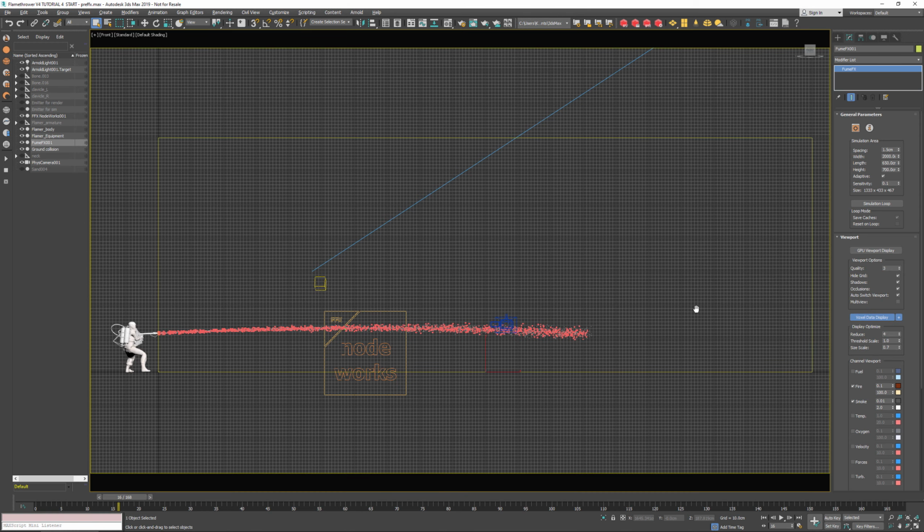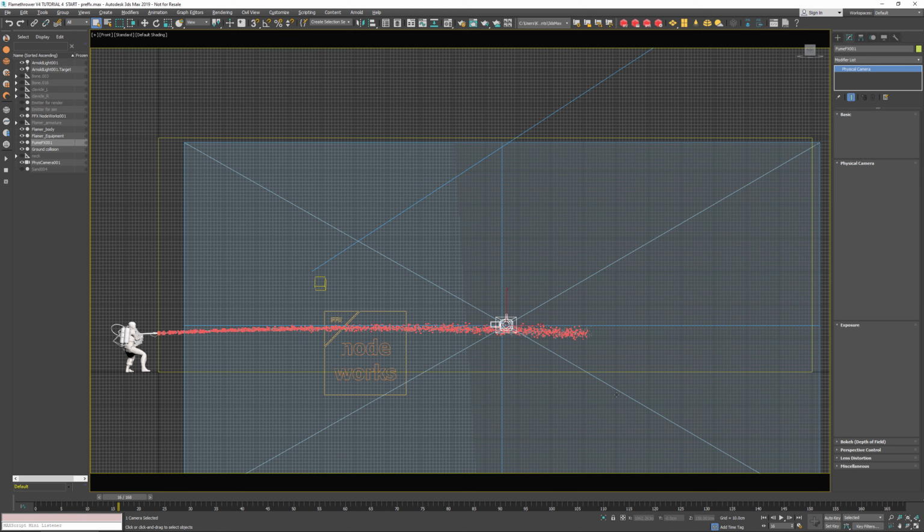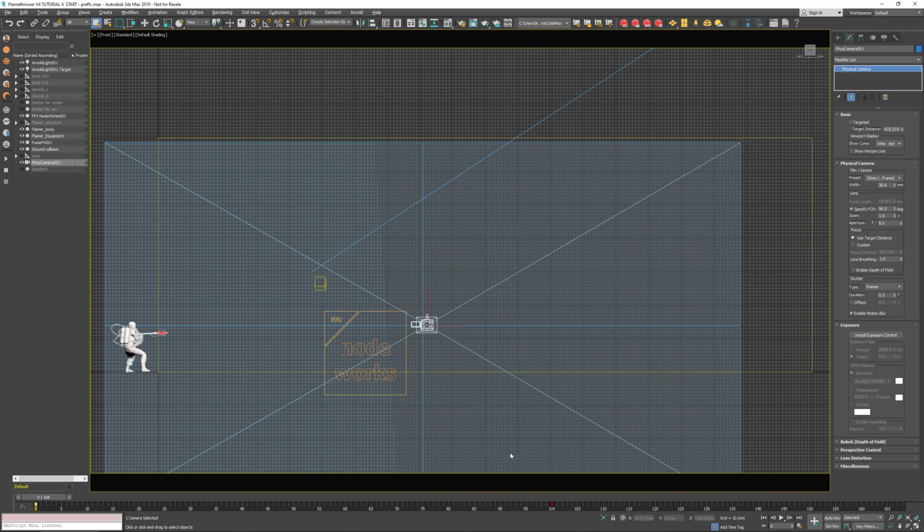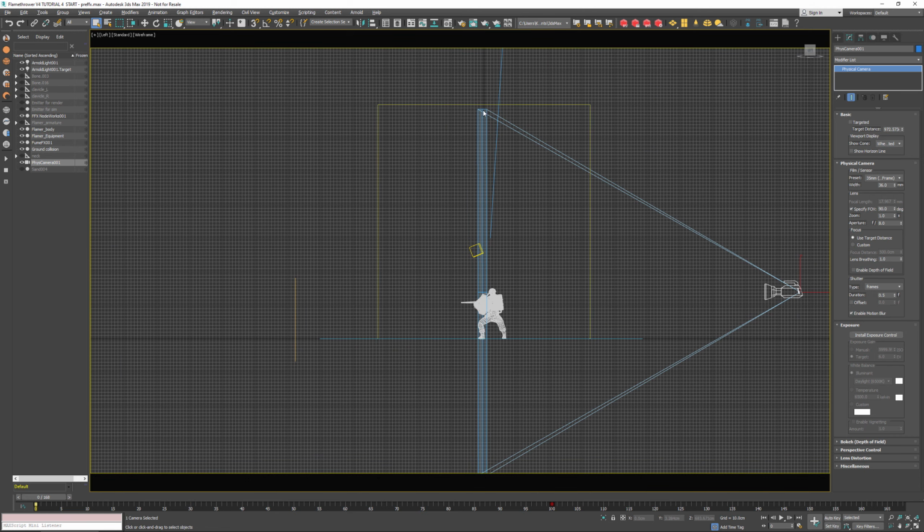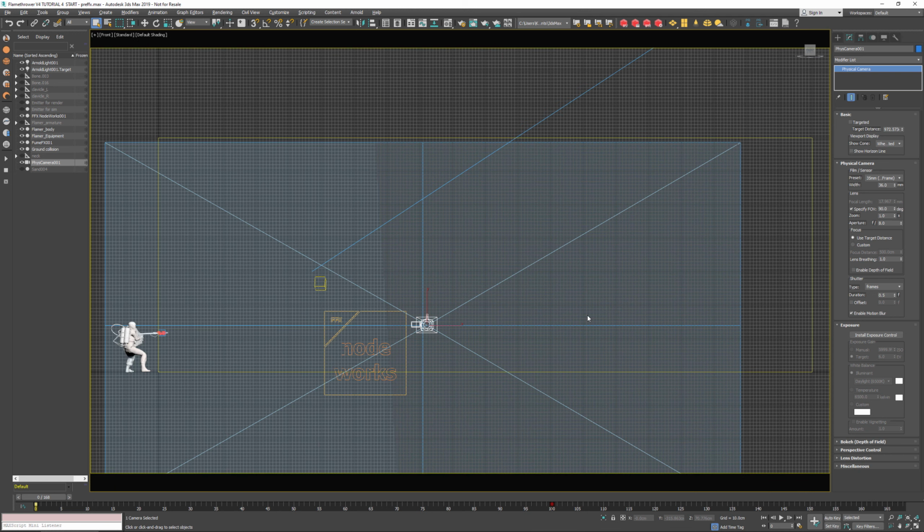So now about the FumeFX setup. The grid is very large, as you can see, as the grid spacing is only 1.5 centimeter. The grid height was not so tough to determine. I've set it so that the height covers the field of view, so if any smoke hits the top of the grid, we're not going to see it. And the width of the grid is set from an experiment from the previous simulation runs.